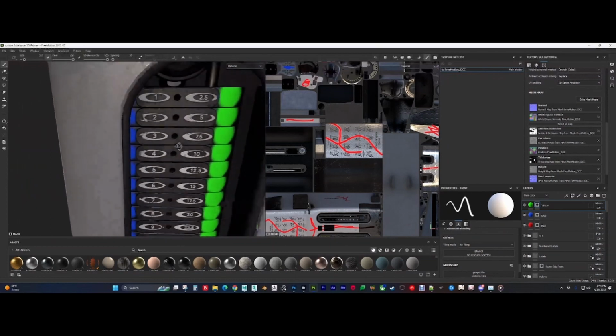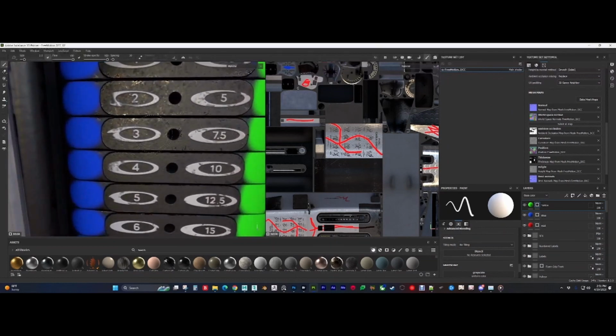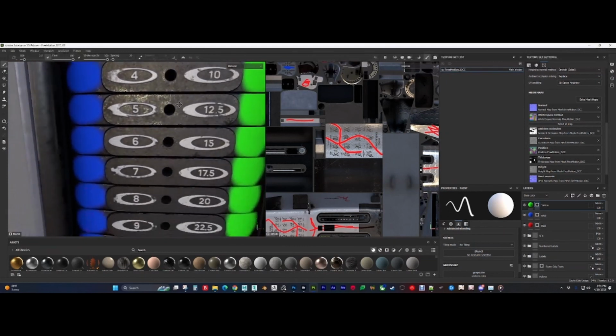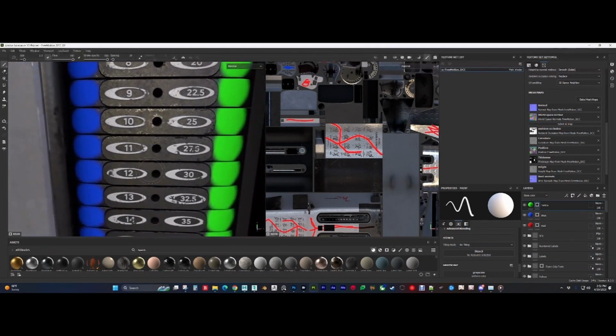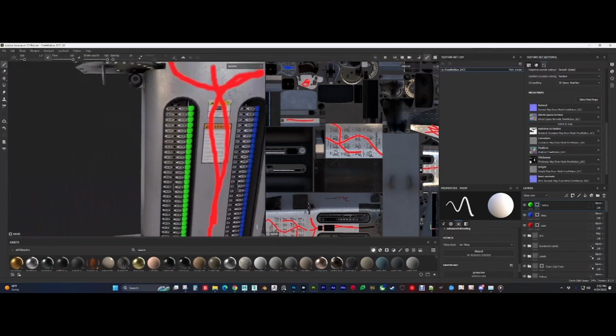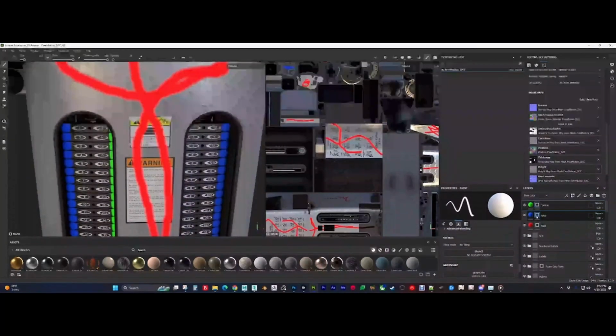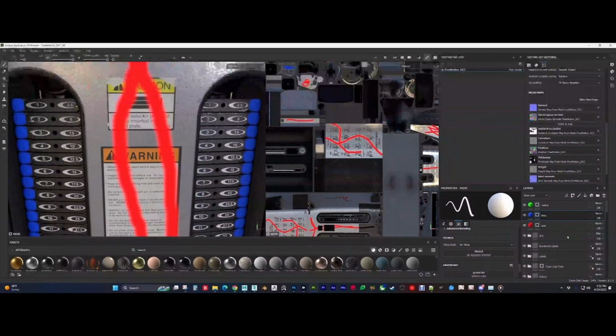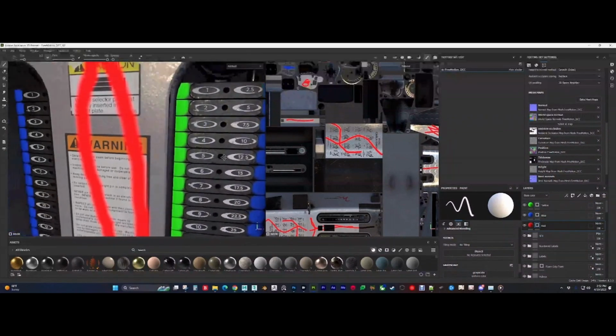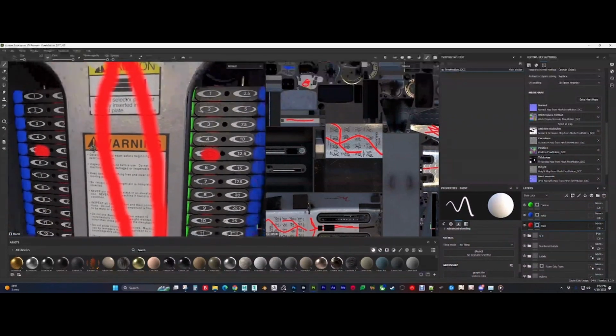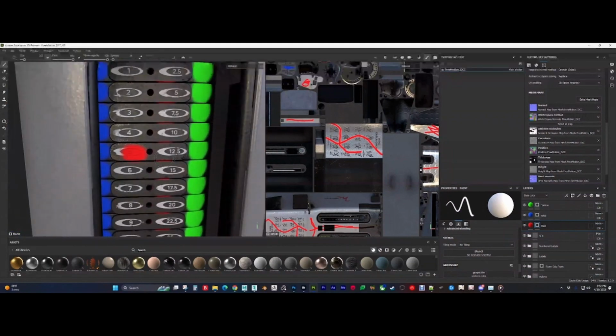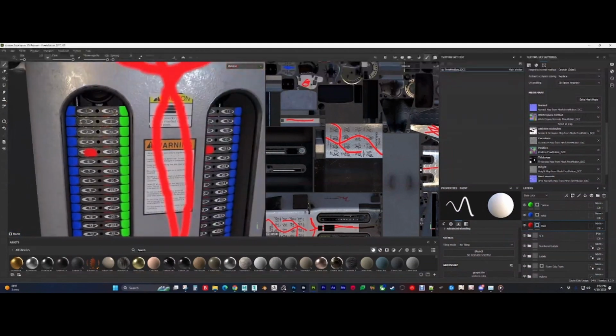And this is the reason why I need the face plates to be individually unwrapped, just because they were unique for stamping the textures on them. All of the numbers had to be unique, so that geometry cannot be stacked, but it can be mirrored. In this case, it's mirrored on both sides. If I cover up that 5 there, you can see it's covered up the 5 there. So in this case, these two are stacked, but the rest of them are independent. They all have a pair pretty much.